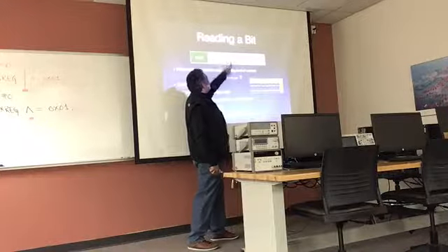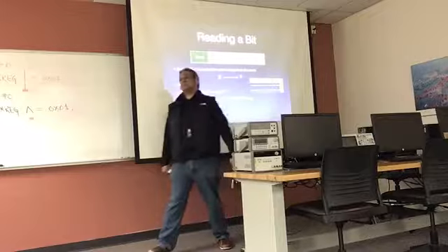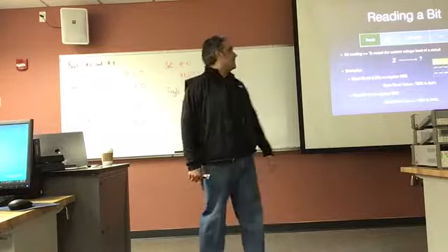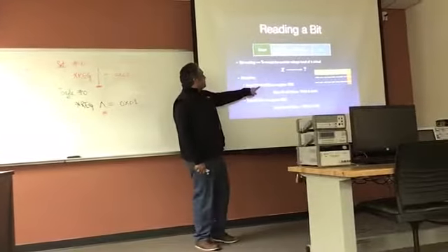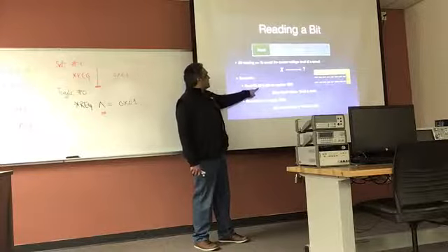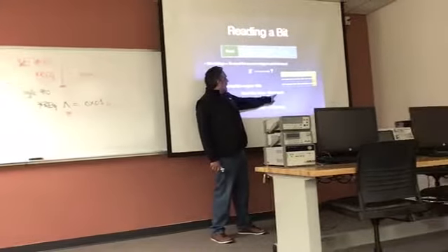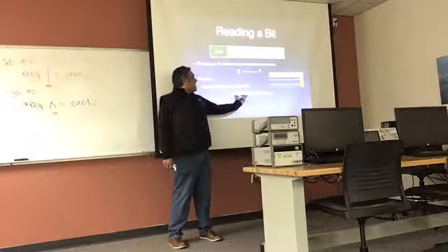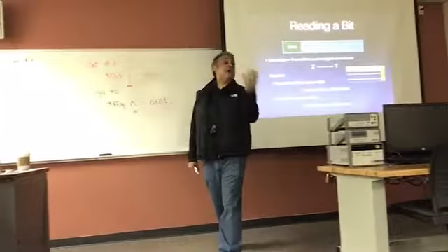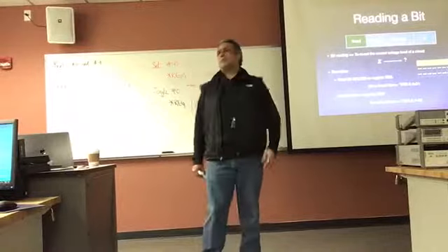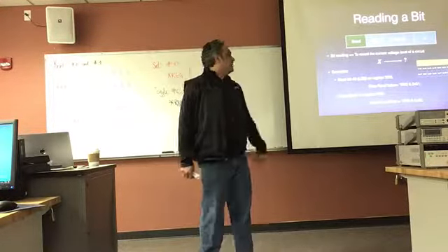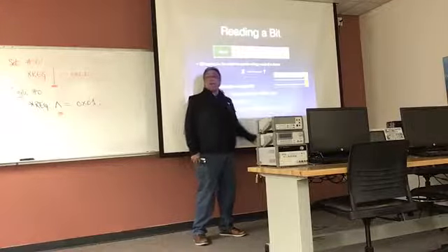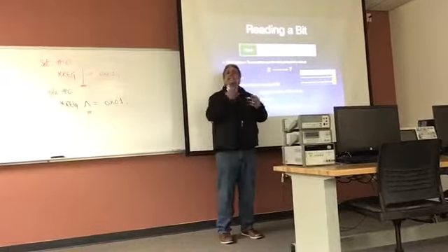So you're going to have X and your mask. And it uses a positive masking. So you pick the spots that you're going to inspect. Okay? So, for example, back to bit 0. If I want to read what's on bit 0, you're going to have reg and bit location. Now, if there is an equal sign, it better be into a variable that is not your register. It could be some other variable that you put in RAM maybe. So you create a variable, you call it X or whatever, and then you simply read a value and you can store it. Or you can read a value and use it. Right? There's all kinds of things we can do with it.